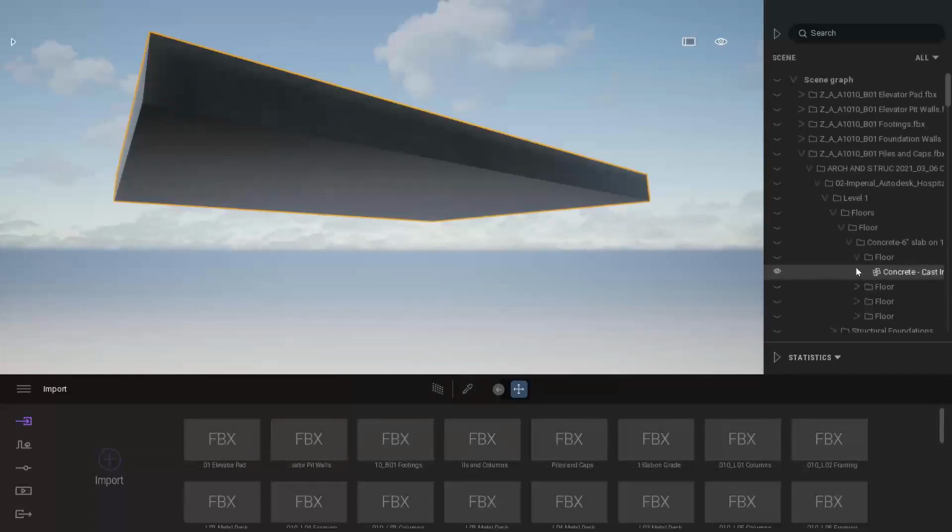The reason I'm mentioning this is this has improved with the Datasmith. I would potentially just have the one level of hierarchy based on the name of the export, and then all of the elements included in that export directly underneath that single folder. So once you've brought these things in, you do have the ability to control and isolate individual elements. I wanted to avoid most of that work once I got into Twinmotion.